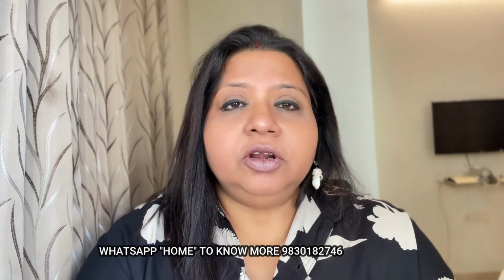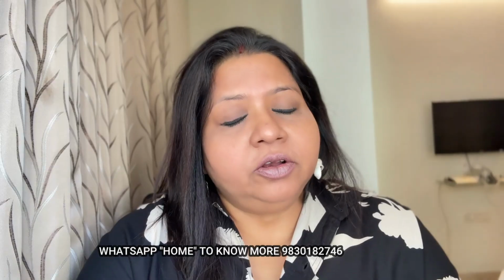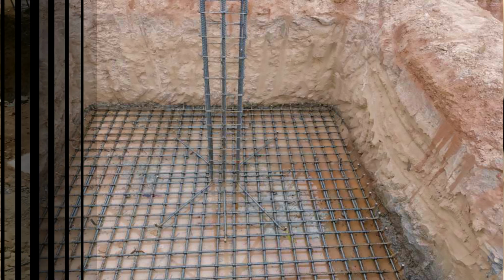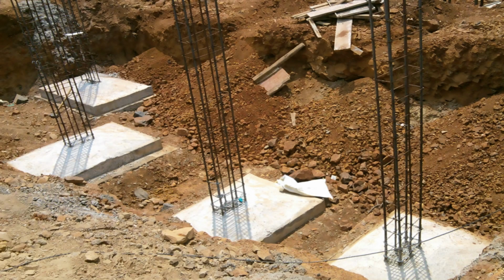Because we are discussing a two-storied building, we will only discuss a shallow foundation or a normal footing in this video. That is a concrete structure which is squarish or rectangular in shape, as you can see on the screen. And beneath the footing, you need to keep two protective layers, one of which is brick flat soling, and the other is plain cement concrete. Both will be 75 mm or 3 inches thick. And above that, we will place the foundation.